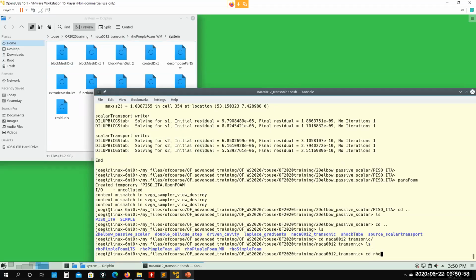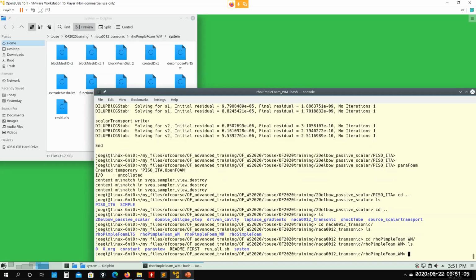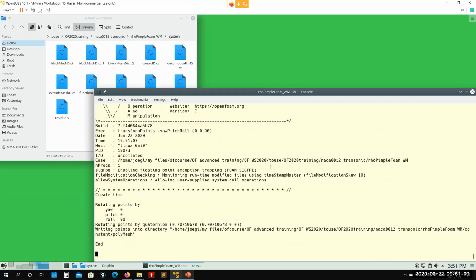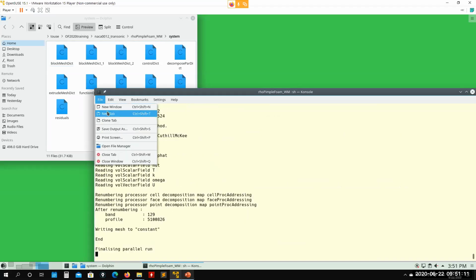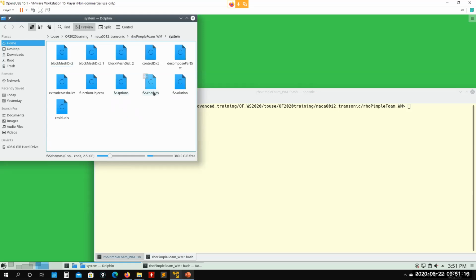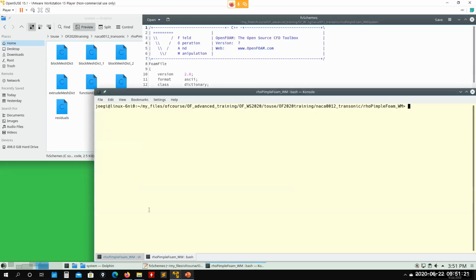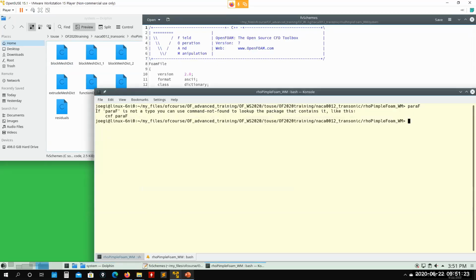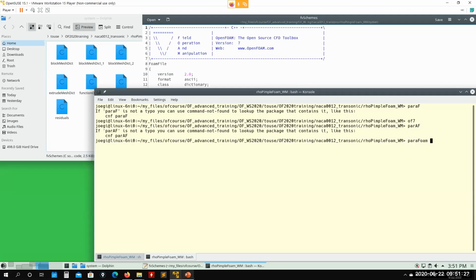So if I go run pimpleFoam, we're probably going to have time to post-process. I will run it, but in the meantime, this one is also running, so it will run in parallel with 4 cores, so be careful. So basically, look at my case. First, let's see the mesh. Okay, so what we're solving. In the next 8 minutes, let's try to do this.